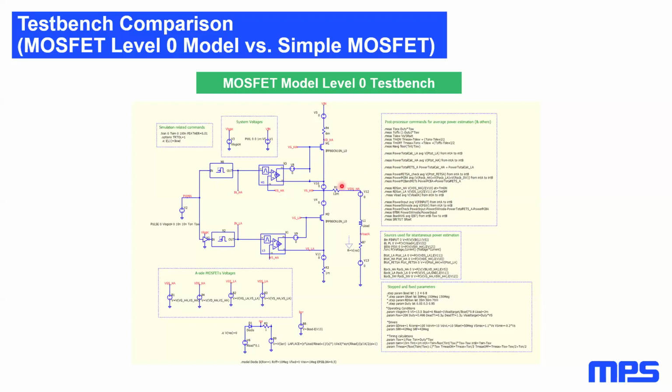In this way, we can superimpose a desired slew rate or a list of slew rates in case of stepped simulations, and all this without worrying about setting up the driver with the right strength for each step. The consequence of this approach is that the capacitances and the gate charges are almost irrelevant for the MOSFET losses estimation, since the trajectory of the operating point during the switching events will be determined by the controlling drivers.